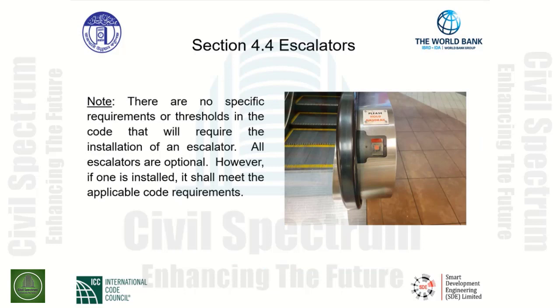A note to the code user: there are no specific requirements or thresholds in the code that will require the installation of an escalator. All escalators are optional. However, if one is installed, it shall meet the applicable code requirements.